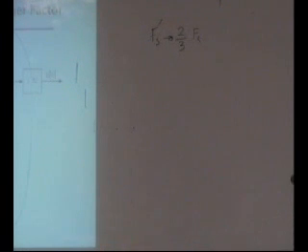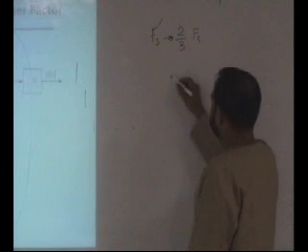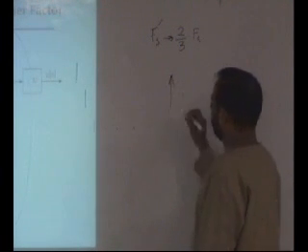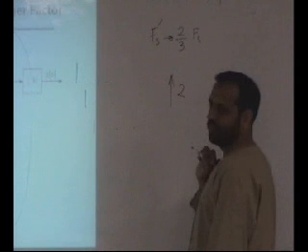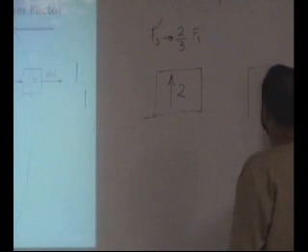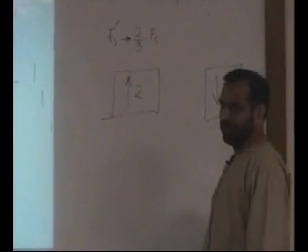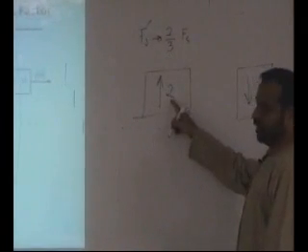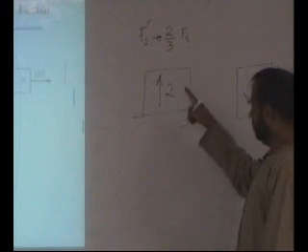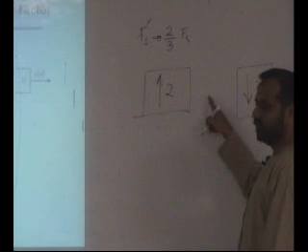So you need to do this. First you increase the sampling rate by 2, then you decrease the sampling rate by 3. We know whenever you are upsampling, you insert zeros and then pass it through a filter.